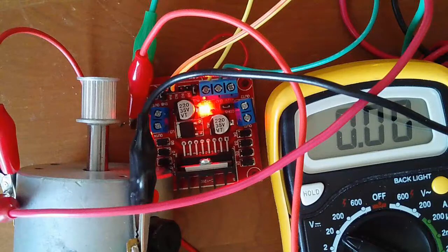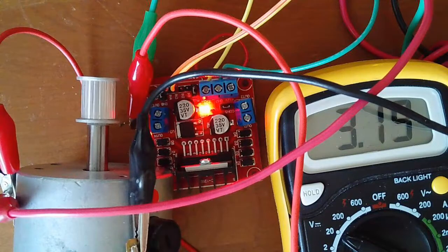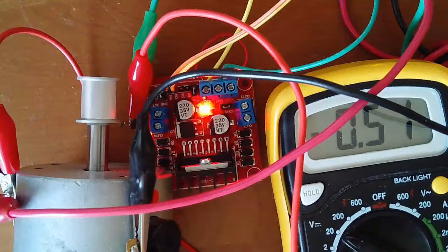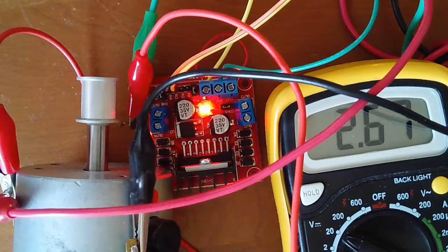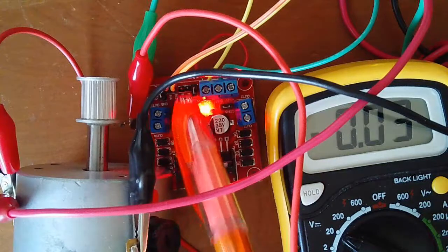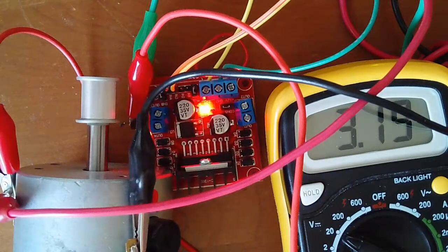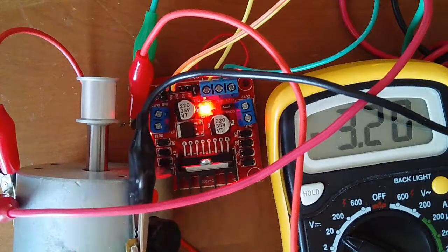To illustrate that, here I've got an H-bridge. This is a little H-bridge that we're going to be talking about later in this class. It's off of eBay for $1.98 out of China. Actually a really nice H-bridge, capable of 3 amps. I've got 2 wires controlling it. That comes from a microprocessor. The processor is a wimp. It can't drive a DC motor, but using an H-bridge, I can drive the DC motor.